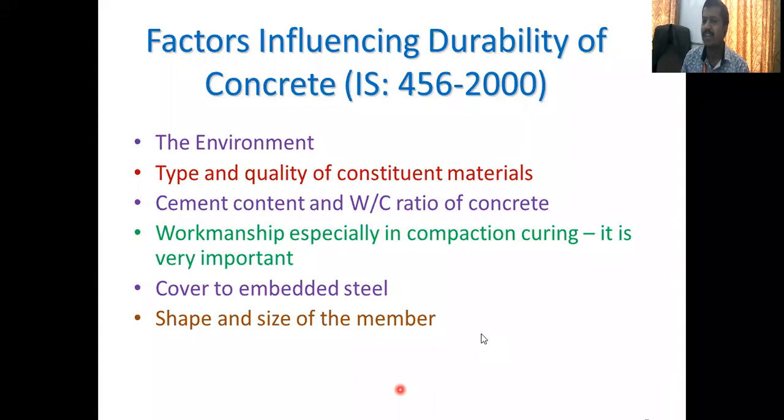So it is going to be maintained within some distance, and that you call the clear cover. Then this clear cover is different for different structural elements like your slab, beam, column, footing. Okay, then how much is this distance? For the slab you are going to provide a clear cover of around 15 to 25 mm. For the beam you can provide 20 up to 25 mm, for the column up to 40 mm, and for the footing also up to 40 mm clear cover.